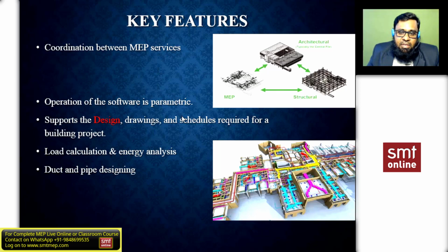Next, duct and pipe designing. So we don't require a separate duct sizer or pipe sizer in Revit, because Revit offers tools for duct and pipe sizing as per the required methods. You can expect different methods for duct sizing, like the equal friction method, static regain method or velocity method. Even for piping you can go for the velocity method or the combined velocity plus friction, etc. So no additional duct sizer or pipe sizer is required. You can use the inbuilt option within the software.